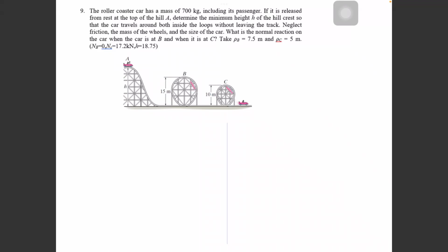Okay, so you need to do conservation of energy lah. Okay, so it said that it's no friction. Okay, so neglect the friction. So you can use conservation of energy T1 plus, dalam case ni is no spring. Okay, it's no spring, so you have only one potential energy which is due to weight. So we have Vg1 is equals to T2 plus Vg2, right? It depends. Kalau kita pilih between point A and B, you can just write down as TA plus VGA equals to TB plus VGB. Okay, it's only between 2 points, either AB or either AC. Okay. So this is what it looks like. Your free body diagram. Okay.